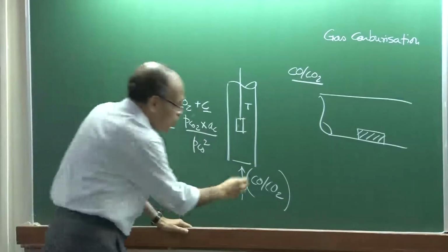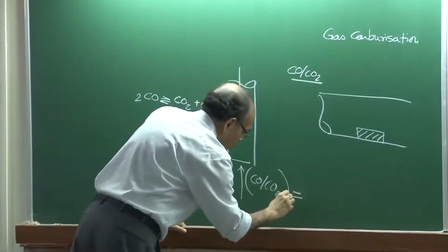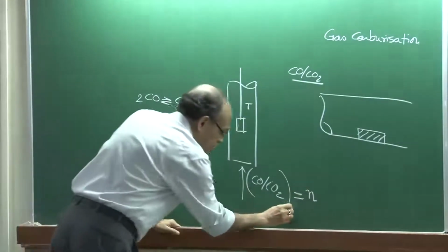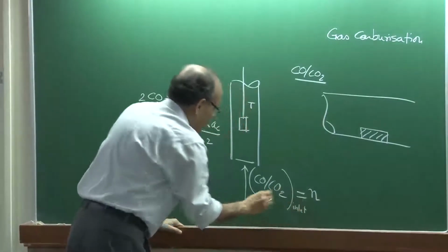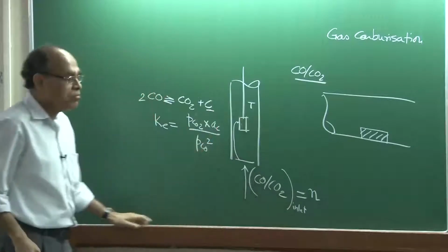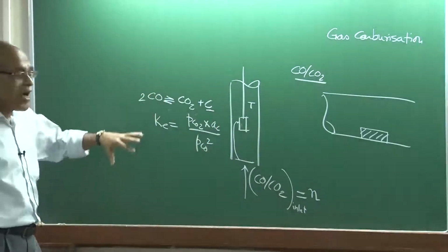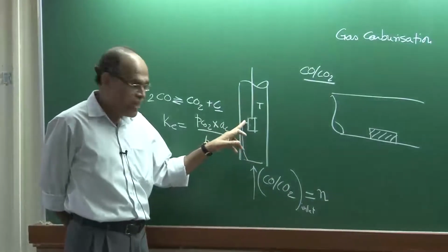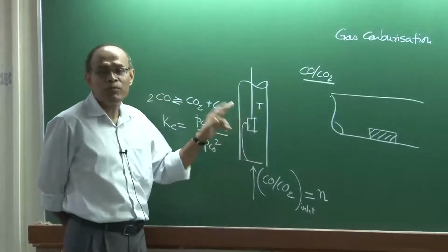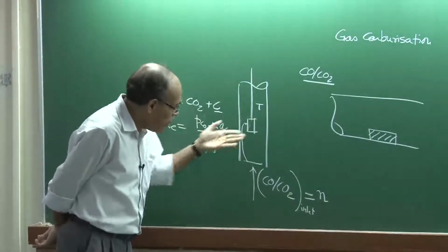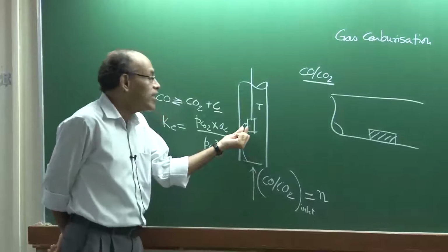We also know the inlet ratio, and we can expect the inlet ratio to be prevalent right up to the solid surface, because we are assuming that it is neither the boundary layer transport nor the bulk transport which is important, but what determines the rate of diffusion and the growth of the carbide layer is dictated by pure diffusion.